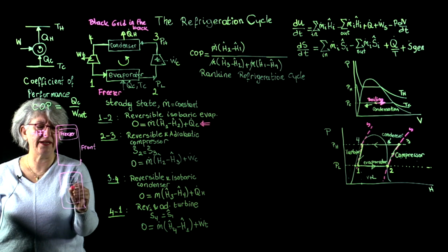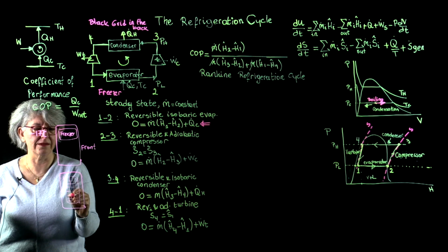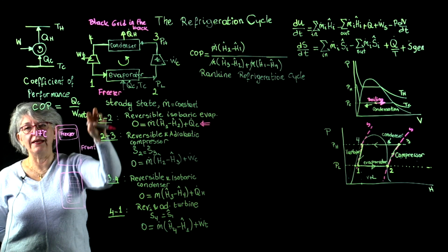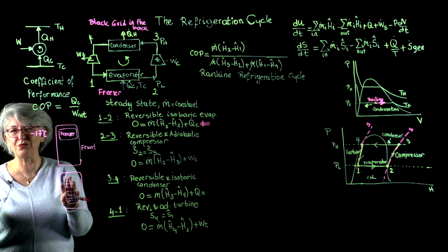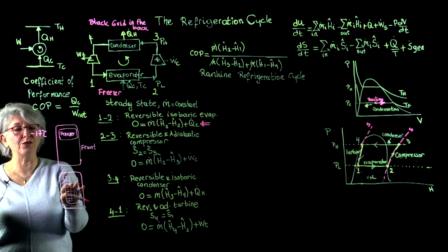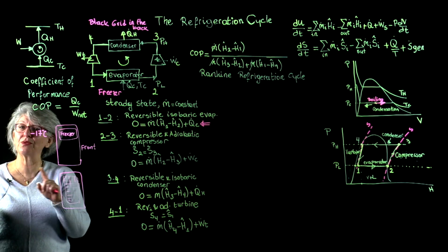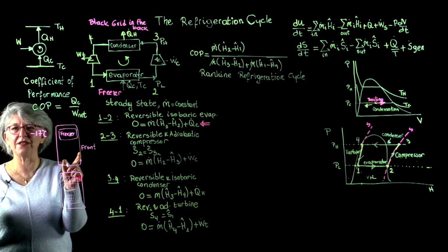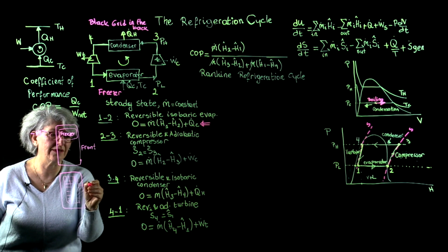This dark black grid is the condenser. And the reason we have this black huge grid is to provide the surface area for efficient heat transfer. We are going to condense our fluid and we are going to discard our heat to the room, and the temperature gradient is very small. To compensate for it, we need a little bit high surface area, and this is our condenser.